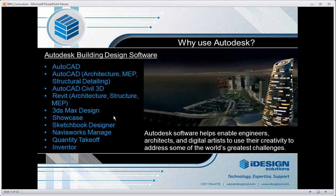You have one shipping container which comprises many parts, but if you're going to use a shipping container in architecture, you might not want to have all those parts of the shipping container within your BIM model. So what Inventor allows you to do is take out the parts that aren't necessarily going to be important, and then when you import that into your Revit model, you have a fairly detailed shipping container, but it's not going to slow down your software because you've taken out all the nuts and bolts that don't really need to be in, say, an architectural plan view.